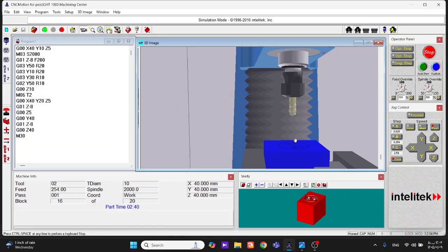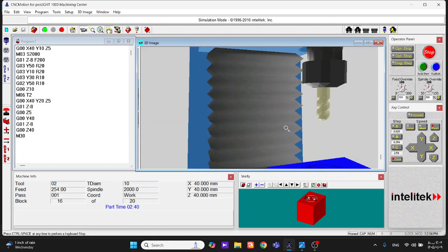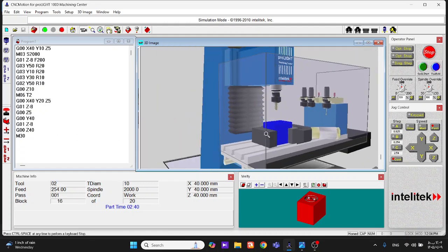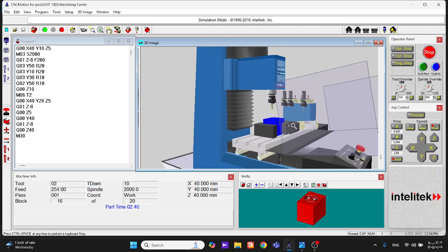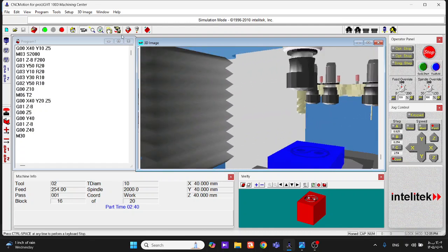And that's it, guys. Congratulations, this is the first time you make some shape or design in your specimen by the CNC machine using G code. And as you see, the spindle is now turning off because we got M30. And even now we can open the shield to check our specimen from a closer view.